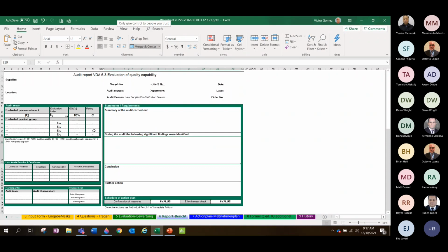That was one case. Another case was a supplier whose measurement equipment and calibration were expired and overdue for 6 months. So we had to stop the audit, and we asked for an immediate correction of that deviation, because at that time, our priority as auditors is to use this audit as a continuous improvement tool. But if you go and there is a huge bleeding in that company, the first thing you have to stop is the bleeding. It's the non-conforming product going out. So our job as auditors is to stop the audit and require immediate actions. As soon as the immediate actions are done, the process is reestablished and the output of the process is good, we can continue with our audit.